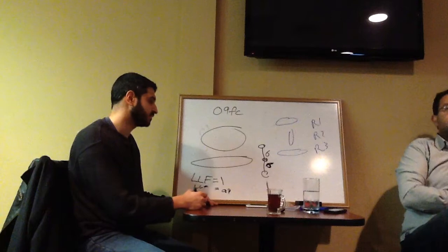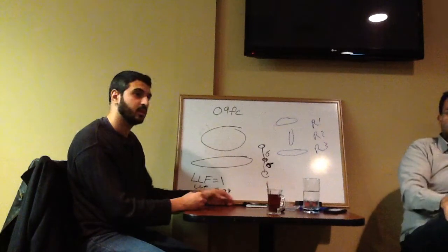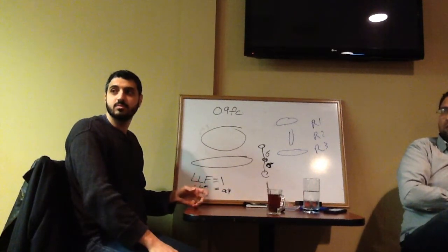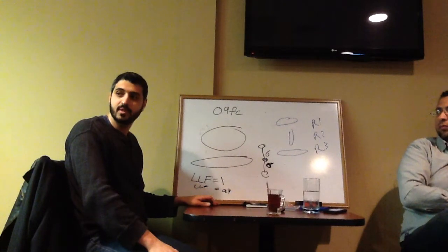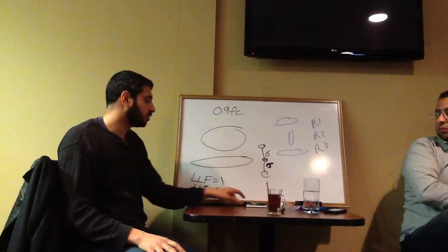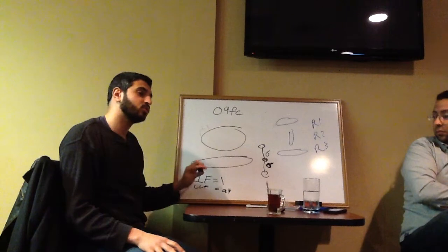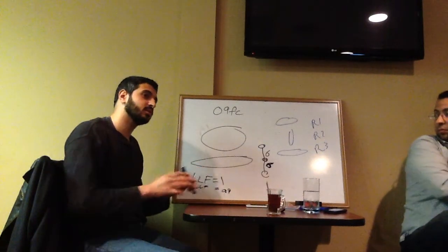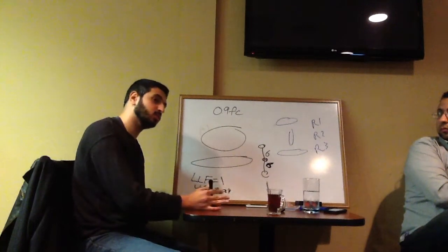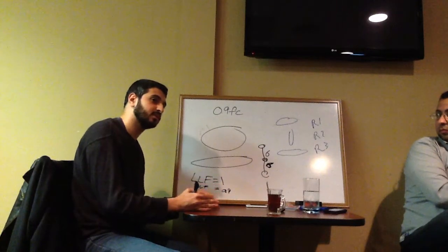So this is a factor, really. They force you to use 0.7. Meaning in 10 years it's losing 30% of its output. So when you run your analysis, usually you run it for the worst case scenario, because you want to guarantee that this light, 10 years from now, 20 years from now, is going to be doing as good as you need it to be. It's not going to fall short.